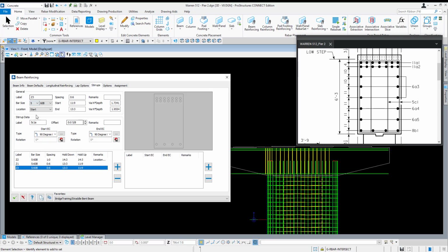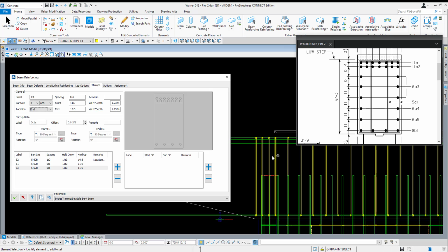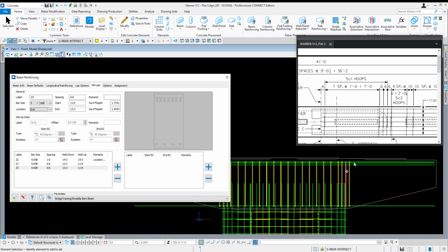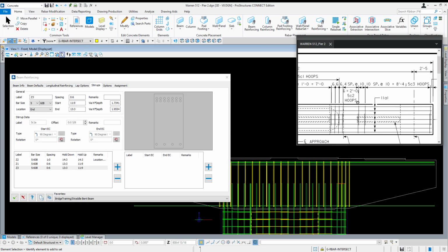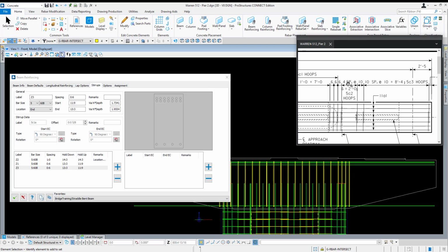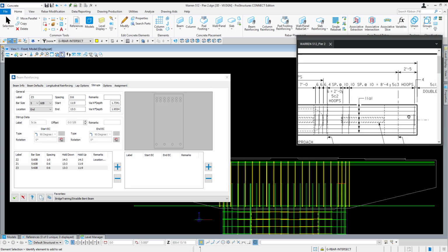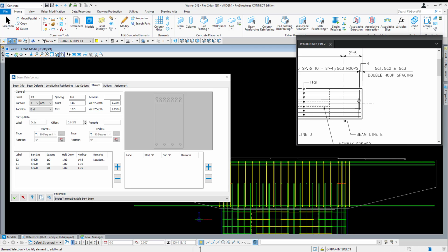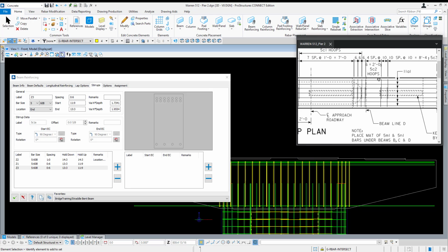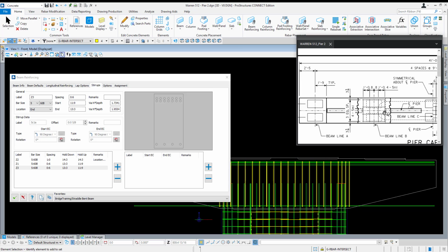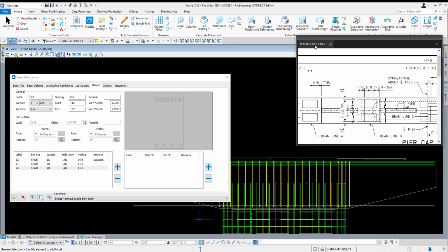And before I continue, looks like I need to adjust. Never made that change to make it at the end there. So now we have our 1 foot spacing in the middle, 6-inch spacing, both ends. And now we go into, it looks like 10-inch spacing all the way down to the end with our tapering sets. So, looks like we're ready to adjust our bottom bars.